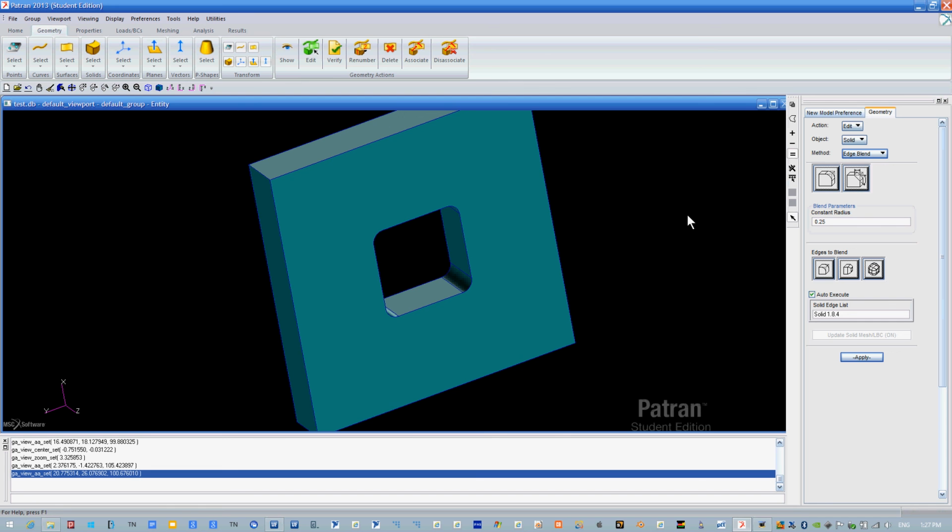Yeah, what I was more saying is, is there any way to get a more accurate FEA result? Yeah, so in real life, you'll never not have a fillet. It might be microscopic, so you can just put something small there. As long as it's not 90 degrees, as long as it's something small, it should be fine. Like if you have anything welded, that's a real life fillet.